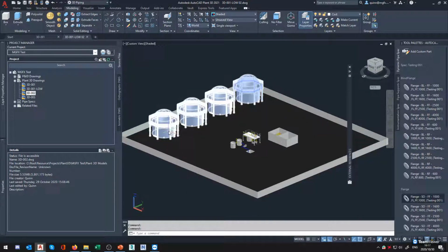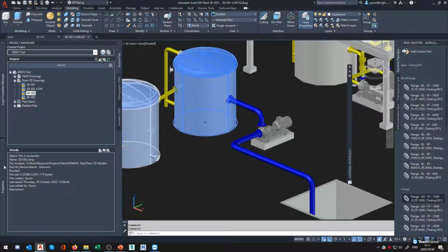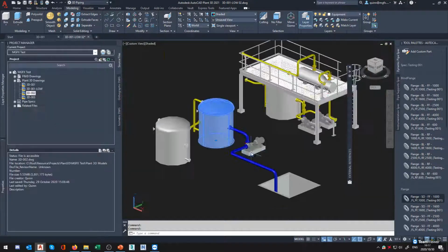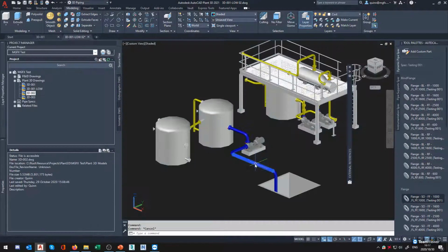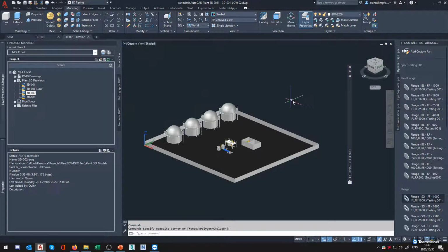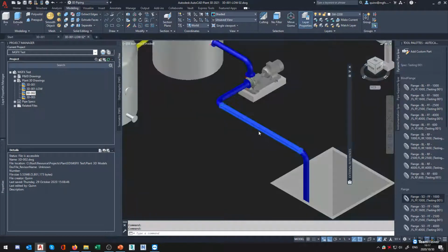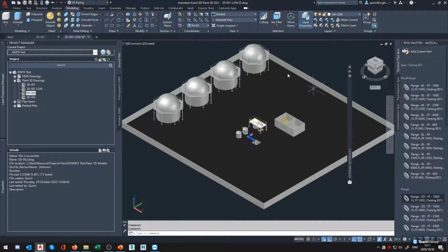There are no breaks or anything. More importantly, you want to try and click on something and go into its properties, and you'll notice everything should be broken into block references. There are no actual details of the parts, etc. So unfortunately, in this case, if you're wanting to go this route, you are going to lose any data you've got on your piping, etc.